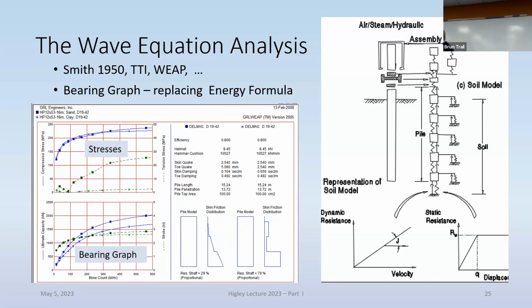The Federal Highway Administration actually supported us in developing a version of it, again in competition with TGI at Texas A&M, which had been in that field much longer, but we were able to verify this wave equation program with our data that we had collected and make a diesel hammer model, which was around here, the hammer of choice.